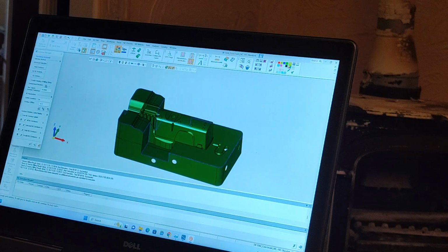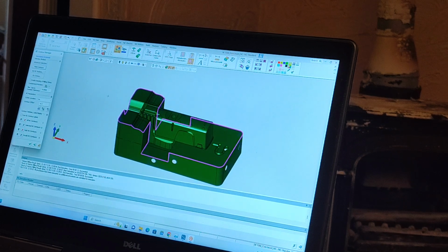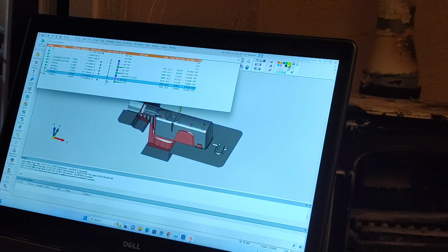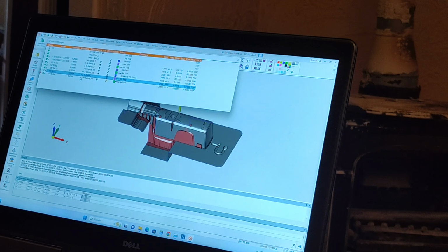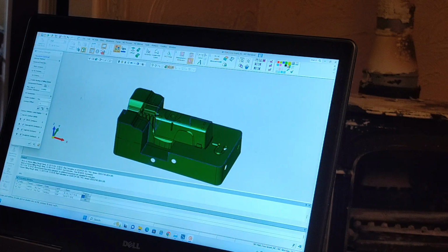You need to choose it. So when I'm selecting a boundary, and if it's a composite curve, I normally choose multi-contours. And it's just one pick, and it automatically picks that chain, not trying to rechain anything. And then save and calculate. And do the same thing for the floors.